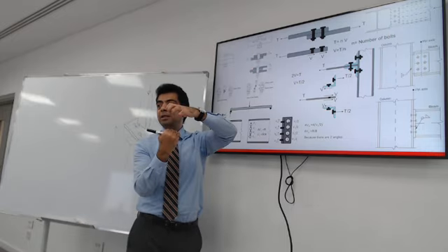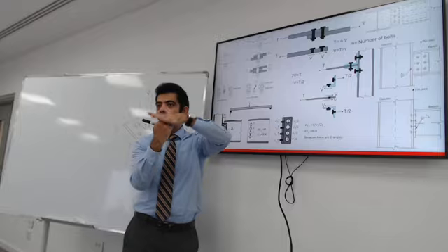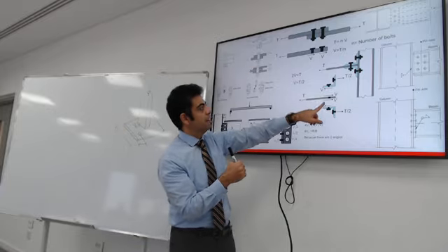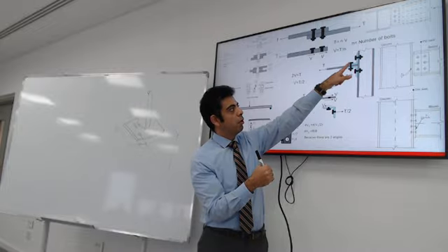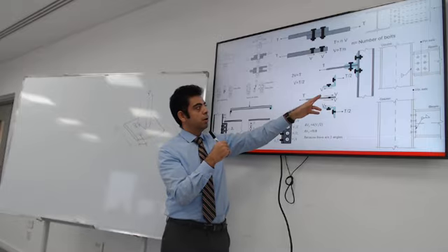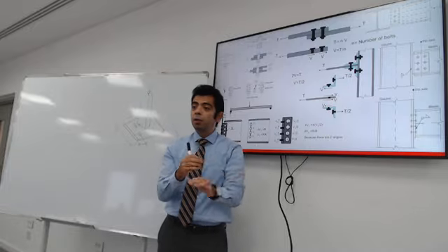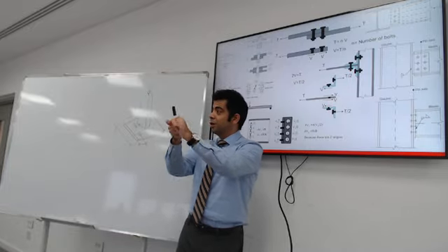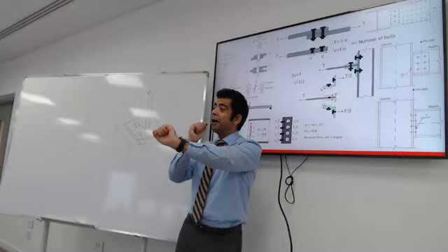You can have tension on the bolt, and it could cause tension force on this connection. So the forces on a bolt can be either shear force trying to shear the bolt, or tension trying to pull the bolt out of the connection.